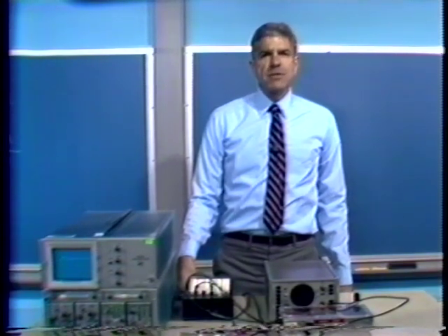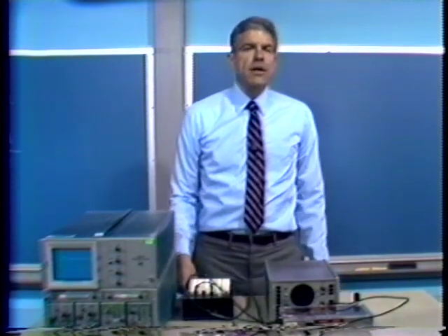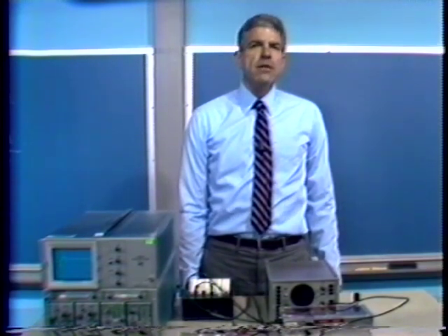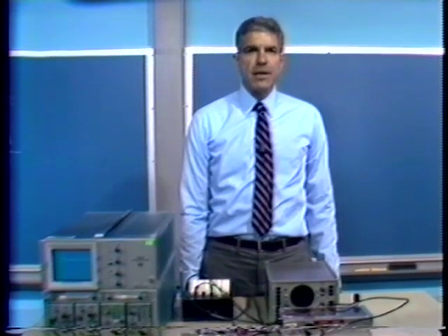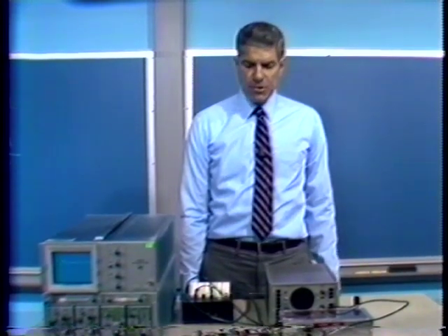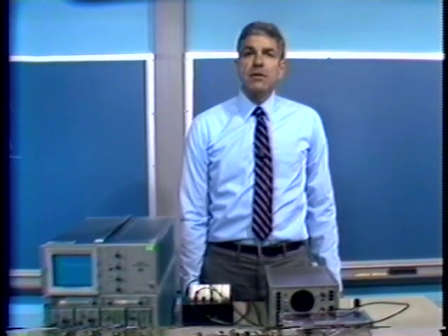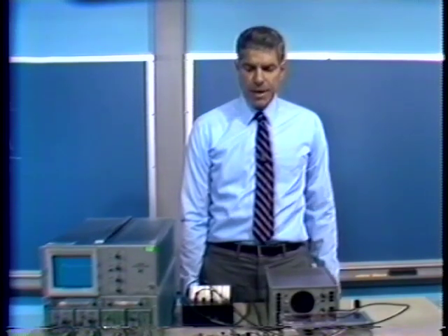Furthermore, even that's optimistic, because when one makes an integrated circuit, there are distributed capacitances associated with all the resistors, for example. So there'd be considerably more degrees of freedom, considerably more modes of energy storage than even the 26. And if we tried to write a complete transfer function, we'd rapidly conclude that the thing was totally analytically intractable.